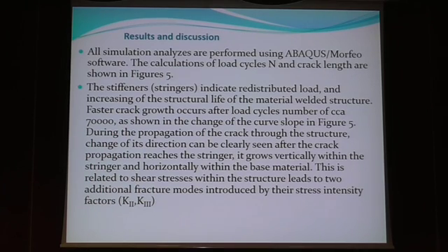I will show graphical results soon as well, but first to make an overview of results and a small discussion about them. So what you will see graphically is load cycles versus crack length. This is as for the fatigue crack growth. And then also for the fatigue crack growth, you will see how stiffeners indicate the redistribution of the load, and thus they would increase, of course, as we expect them, the structural life of the welded joint.